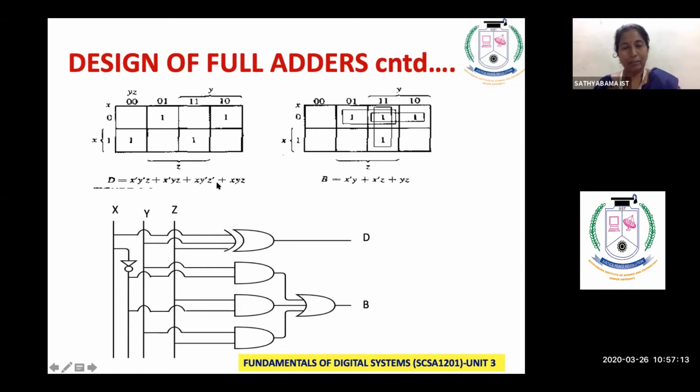You take a paper and check whether x XOR y, bracket, XOR with z is giving you this expression. It will give you many terms, xyz plus another xyz. You all know xyz plus xyz is xyz. So like that you have to minimize it, and finally you will understand it is nothing but an XOR gate. So it's okay to memorize. Let us not reinvent the wheel.